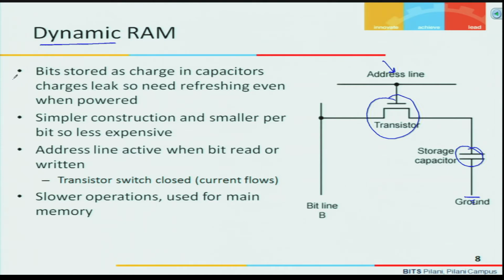So, bits are stored as charge in capacitors, and charge leaks. So, we need refreshing even when powered on. Simple construction compared to the SRAM, because only one transistor and one capacitor are required. So, the size is small, density becomes more, and cost per bit will also be less.